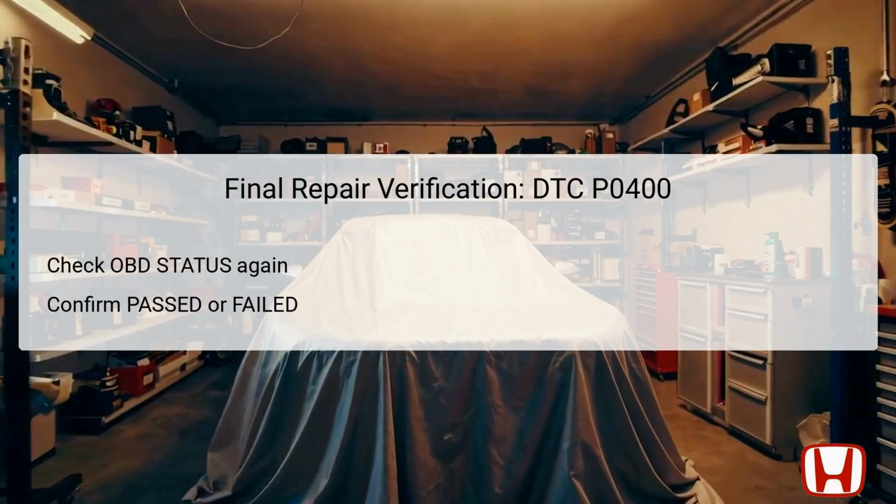In the final repair verification stage, you will monitor the OBD status to evaluate the final outcome of the repairs. After completing the previous steps, the HDS will indicate whether the DTC P0400 has returned and if the status is passed or failed. If the HDS indicates passed, this confirms that the repairs were successful and the EGR system functions without errors. However, if the status is failed, further investigation or rechecking of the components involved is necessary.